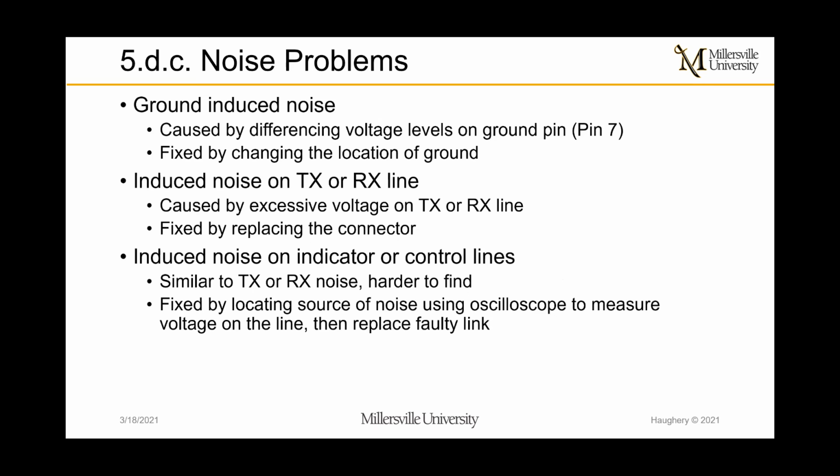So here we have some different noise problems that you may encounter. First of all is ground-induced noise, which is caused by different voltage levels on the ground pin itself. You can fix this by simply changing the location of the ground. You might also have some induced noise on the TX or RX line. This is also caused by excessive voltage across either one of those lines. You can try fixing that by replacing the connector you use for those.